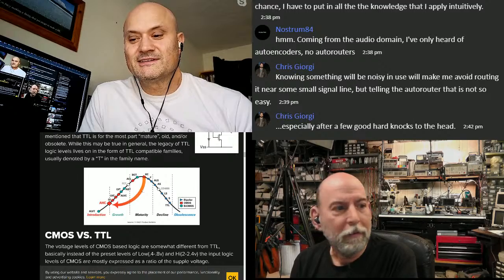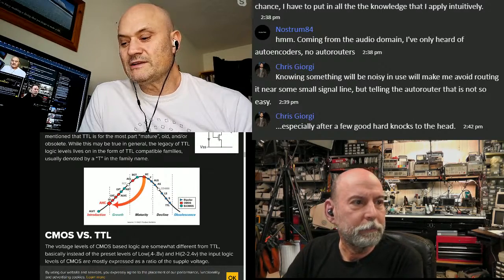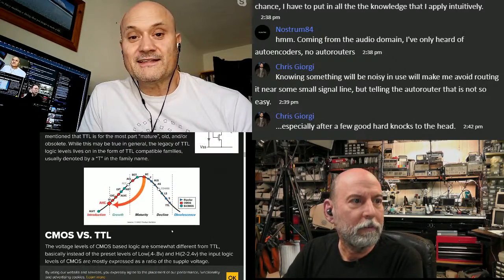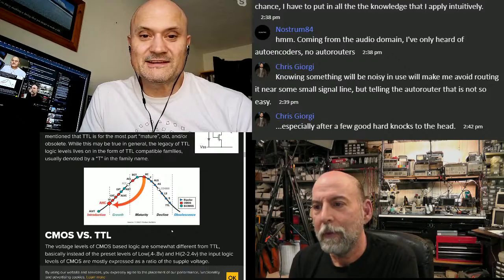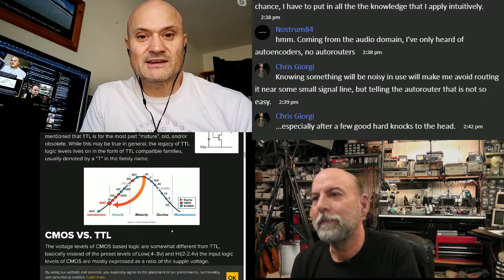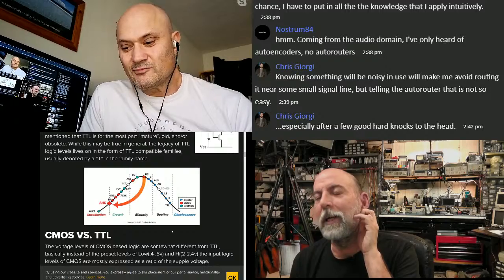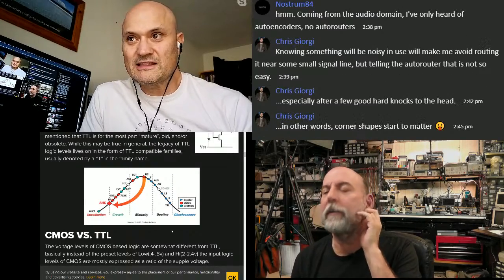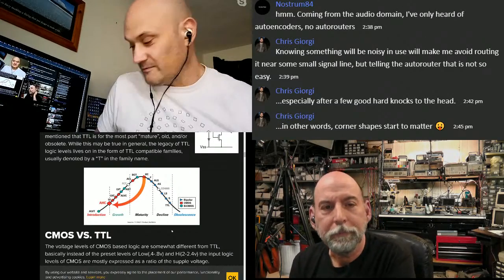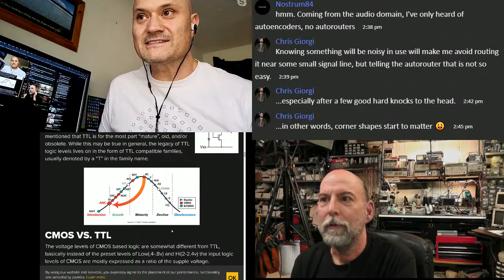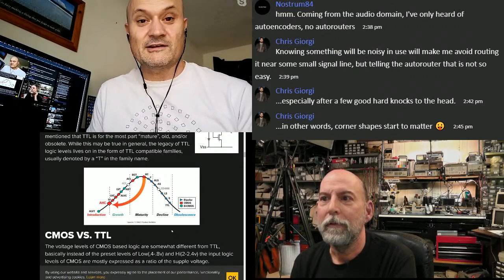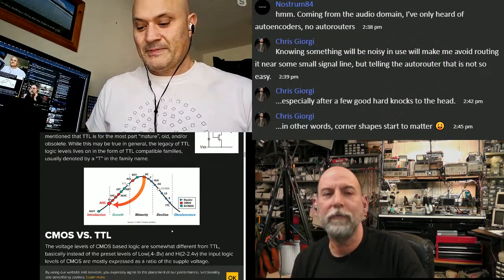Yes. When you may have done nothing wrong, but your semiconductor vendor moves to a new fabrication process where there's a die shrink and everything gets faster. Your clock frequency hasn't changed, your firmware hasn't changed, but suddenly things start going haywire. Right, your edges have changed.